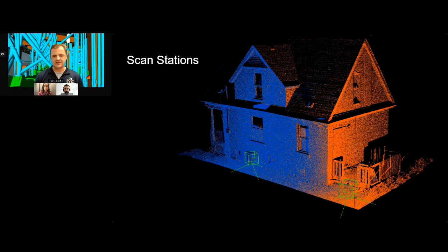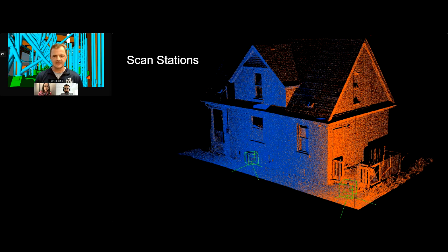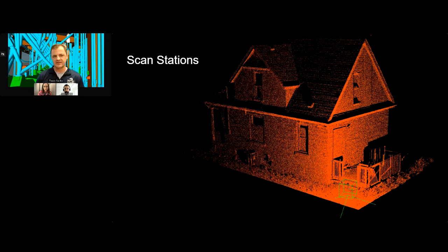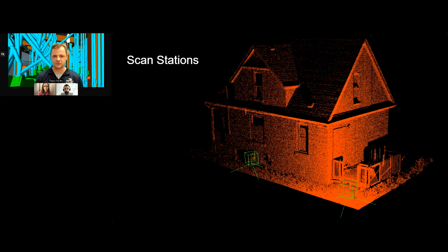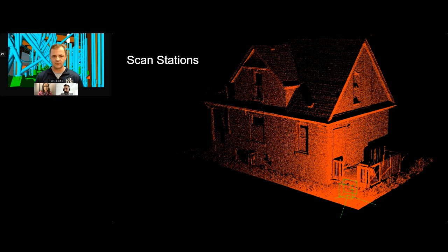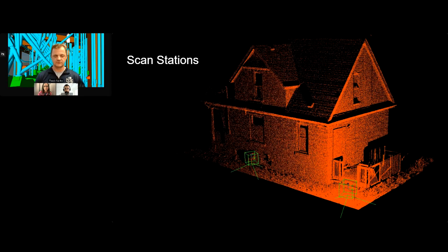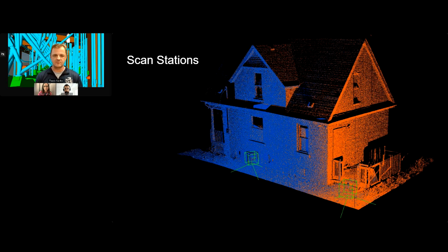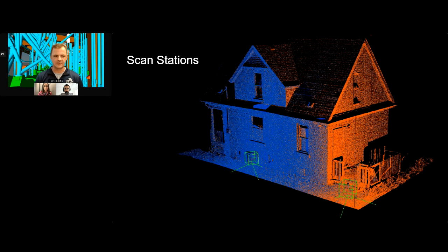So when you're doing terrestrial scanning, you want to know, first of all, what you're scanning, and that will help you determine the setup positions. Because it's only line of sight, you want to make sure that you're capturing all of the object that you're trying to capture. So you'll have to move your scanner into different positions to create a full 3D point cloud, which is basically, because you're measuring up to 2 million points a second, you'll want to make sure that all those points that will create that 3D model will cover everything of what you're going to do.